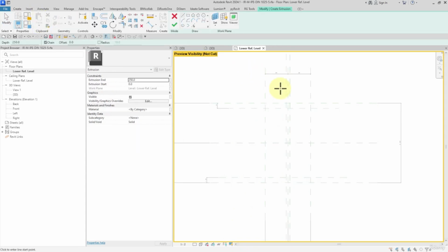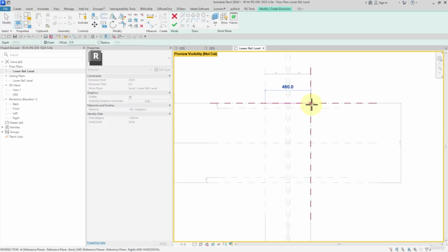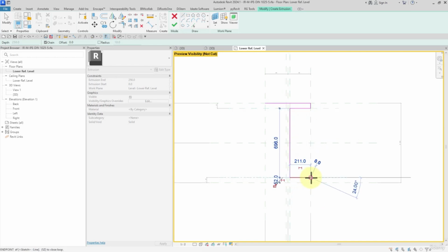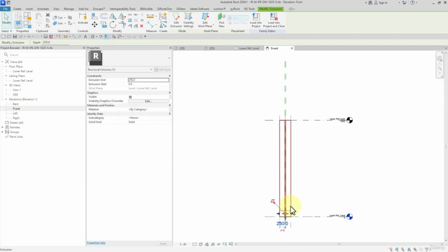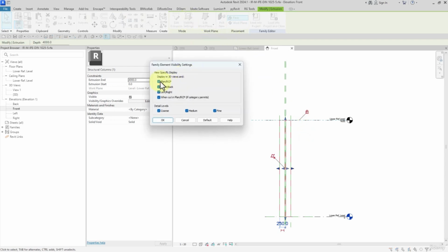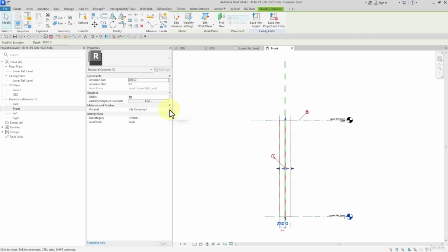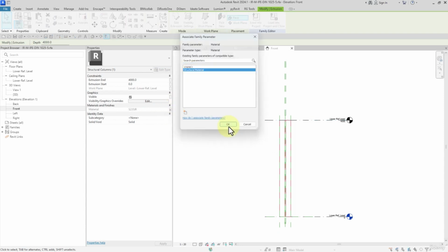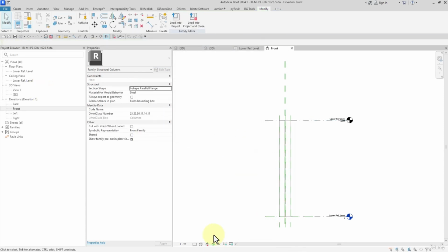Then for the medium, I want to consider another extrusion without fillets for the medium detail level this way. Check this out, finish, and then I connect it to the upper level, unchecking plan and keeping medium. And then for the material I specify this structural. Great.